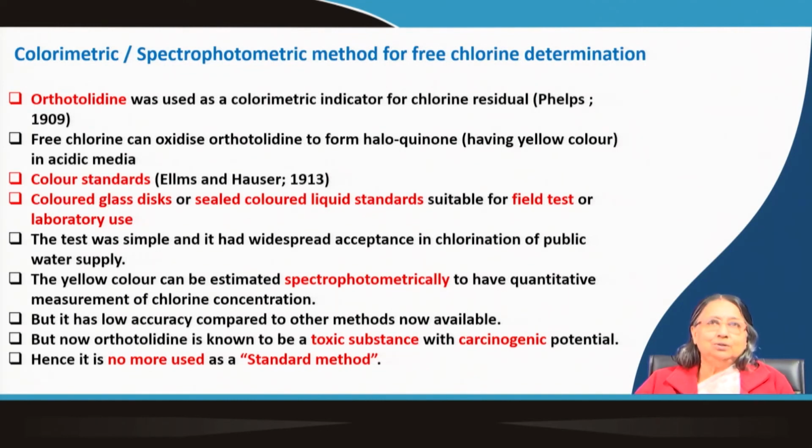Your sample you do the same thing and compare the color. So, comparison with standard color. Sometimes a disc also, some disc has a colored disc, you put it there, your prepared solution is giving some color. So, you match with the discs and then you will know what the concentration is.